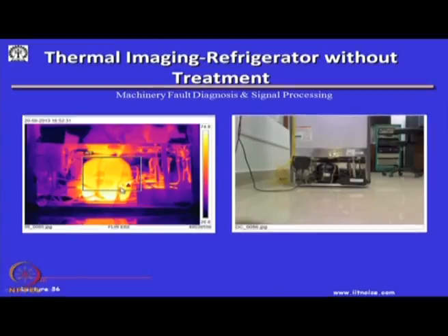Through thermal imaging you can see the temperature of the refrigerator compressor, and we are doing this because we are trying to reduce the noise of this refrigerator through some treatment, and we do not want the compressor temperature to rise abnormally, and that is why we took advantage of thermal imaging, so that in one go we can get a quick image. And you can see these lines are the thermocouple cables. So, quickly in one single shot you can get the view of an image.